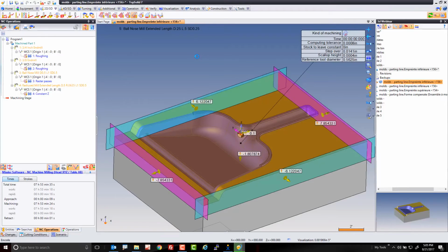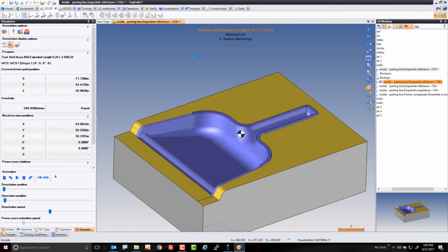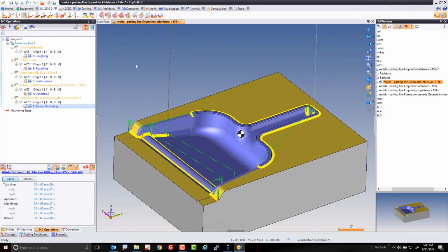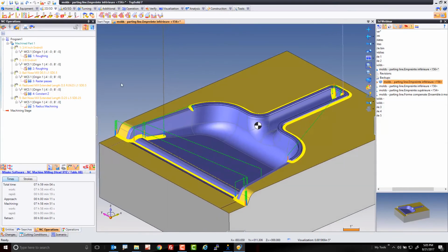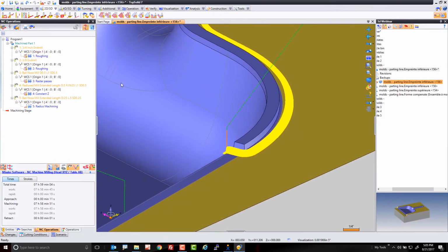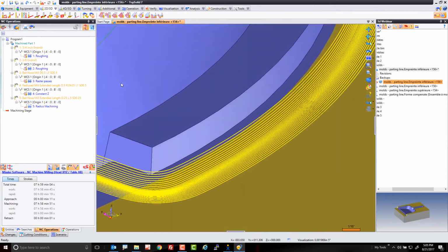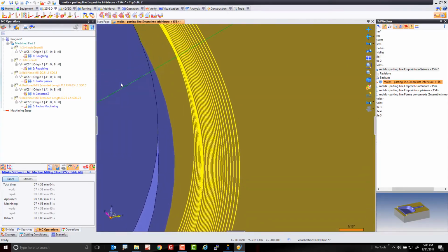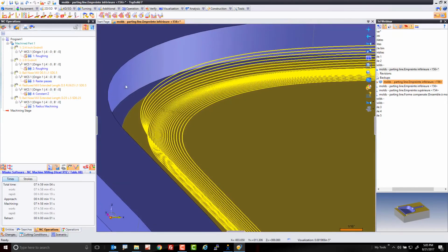And in this case, the solution is going to automatically try to continue machining where the tool of that size could not reach. And if you remember, these are all the areas where it was showing there was still material. Now, if I zoom up on this toolpath, you're going to see that these toolpath algorithms are really, really smart. These are shallow, so it's nibbling in a very smooth way into these corners.